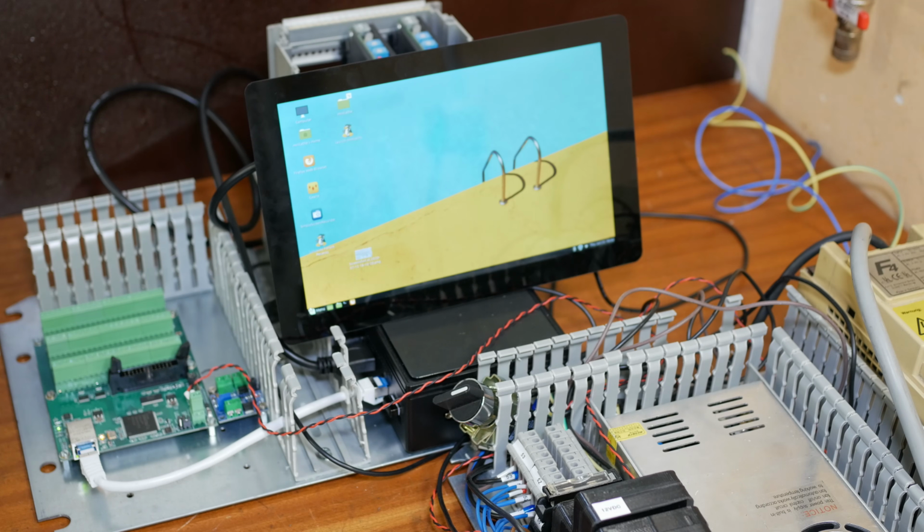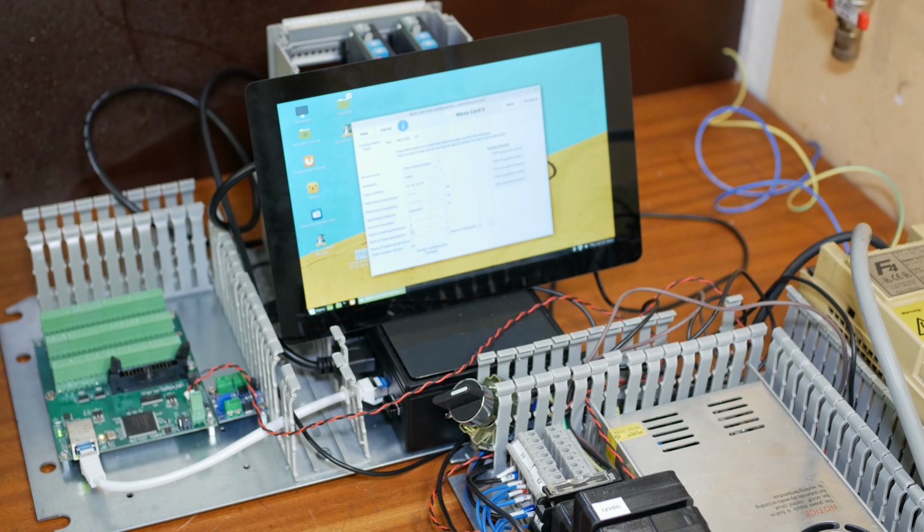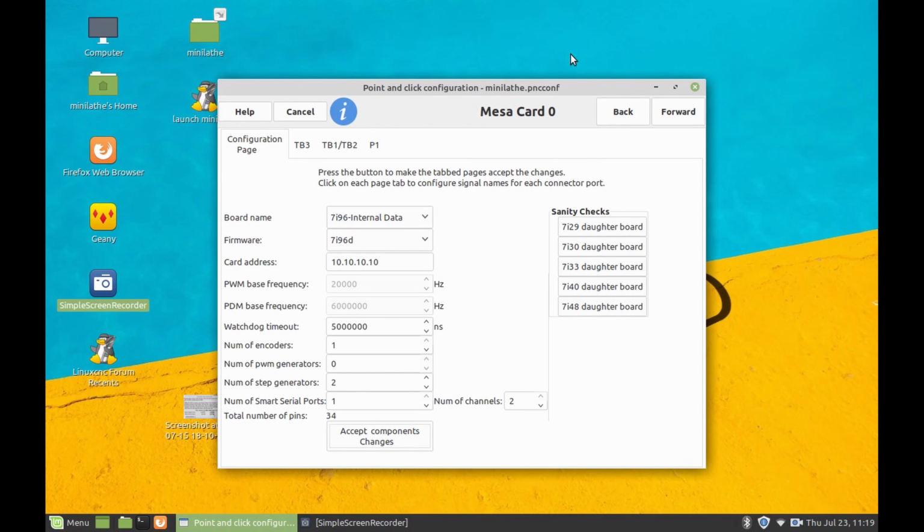In the comment section from last week, a couple of you picked up that I'd made a bit of a mistake in the configuration. I had the number of pulse width modulation generators at 0 for some reason, so that was definitely wrong. Okay, this just keeps jumping back to 0. It looks like this function hasn't been implemented in PnCconf. Which is probably quite normal.